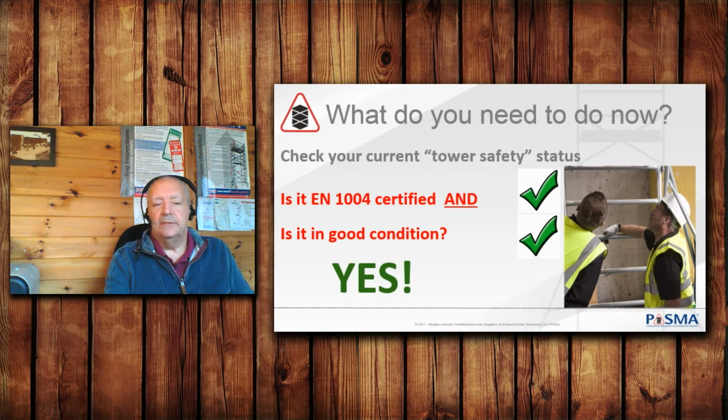But you don't need to replace any existing tower that you can show complies with the previous version of EN 1004. You can still use it whilst it's in good condition, if it was certified to the previous version of EN 1004.